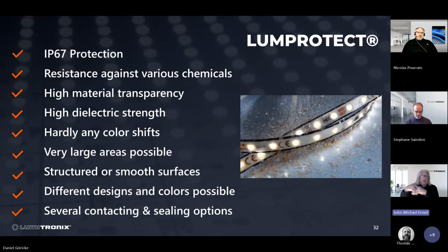Probably the two key benefits of this approach of reaching IP67 in comparison, especially to potting or other silicone approaches, is a very high efficacy on the light output. The material is very transparent, minimum in the 96%. And subsequent to that, a much lower impact of color shift that happens typically when you pot or encapsulate an emitter platform or source. So obviously the colder colors will see a little bit more impact than the warmer range.